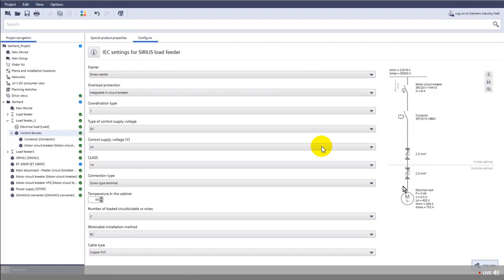Oh, interesting. I thought the cable conductor cross-section needs to be adapted too, but apparently it's good also for that cable length. It has only a major impact on the short circuit conditions. Exactly. It's a really small motor, so that's why your cable dimension doesn't need to change because of the amperage rating here that we have. Very well. Thank you. Cool.